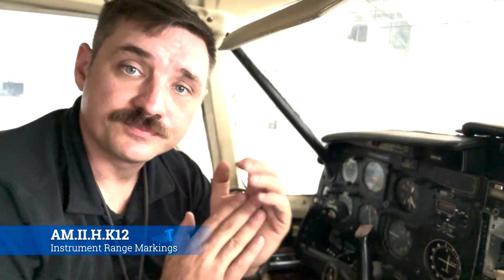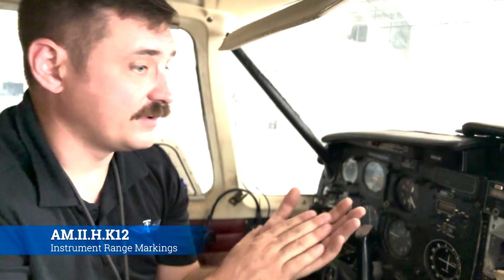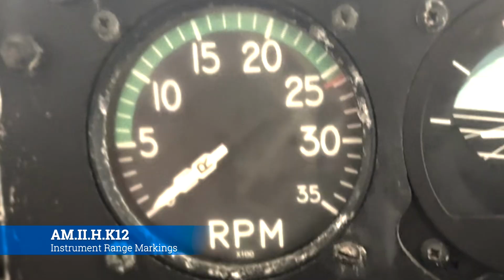Now every single aircraft or instrument has an arc of some variety, or has some sort of marking on there that'll tell you just about that. Green is generally always good, and red is generally always bad, and yellow is kind of in the middle. So our tachometer tells us the same thing: here are the green operating ranges for the engine RPMs, and here's where the engine is going just a little bit too fast. We need to not exceed that, and this is going to come at about 2,600 RPMs right there.